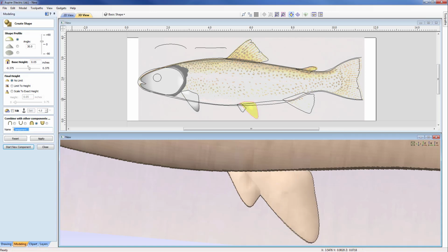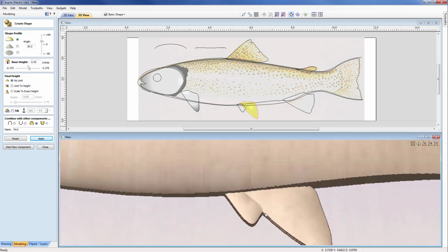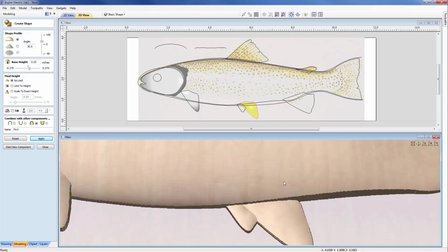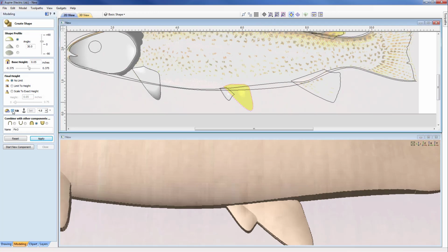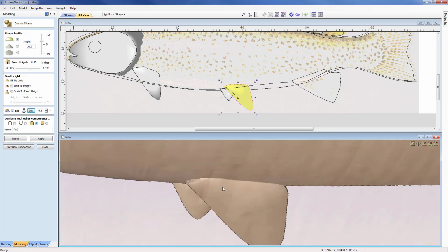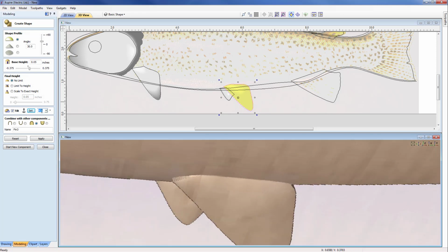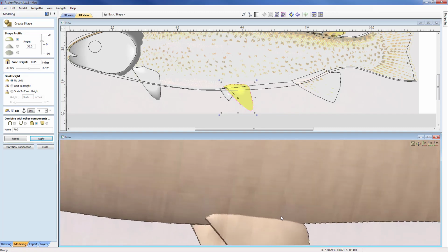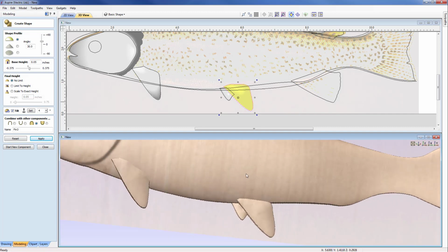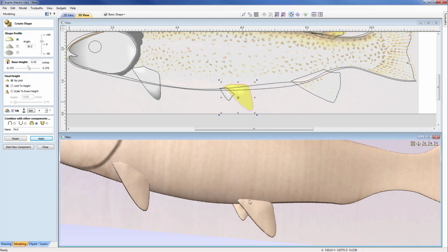This is going to be called fin 3, and one thing I do need to do is address the fact that we have this quite sort of steep face here. We need to make sure the fin is transitioning in up onto the base shape, so we do need to apply a tilt. So I select tilt now, go to set, and just set the direction, and it's currently set to 4.8 as an angle, and if we just twiddle that down, you can see that there. And of course, if I actually decrease this down to 4 and just apply it, that will actually lower that, but of course it does lower the model in the actual base shape, but I think that's still an okay effect, and it means that we don't have to do quite so much smoothing here.